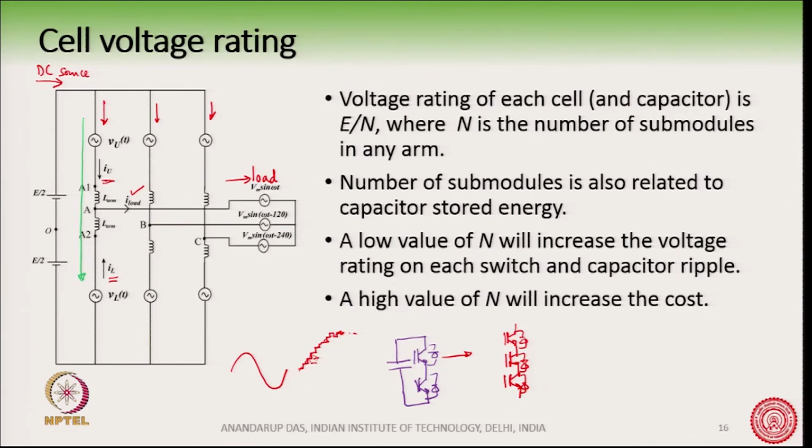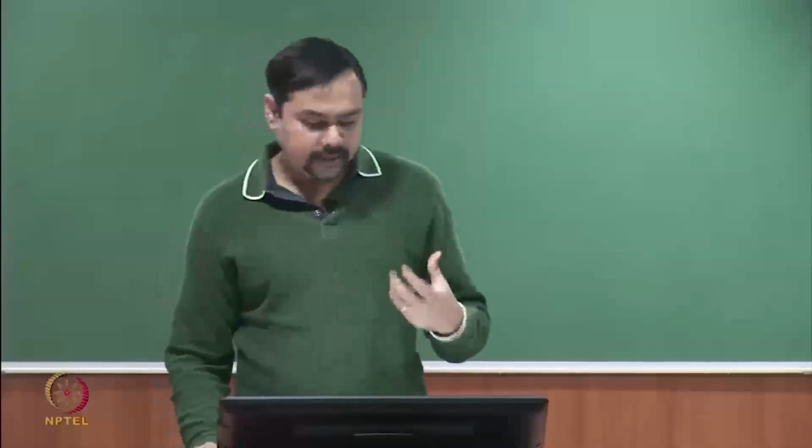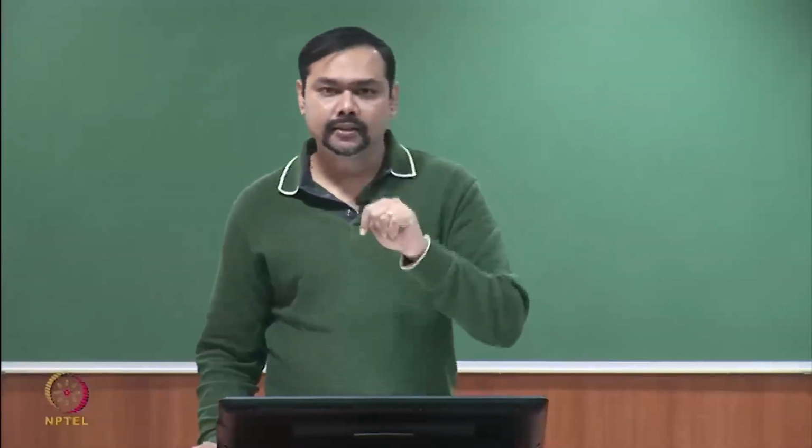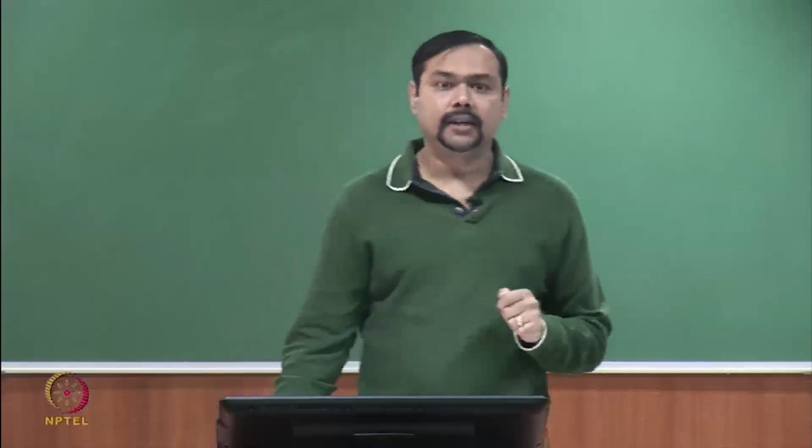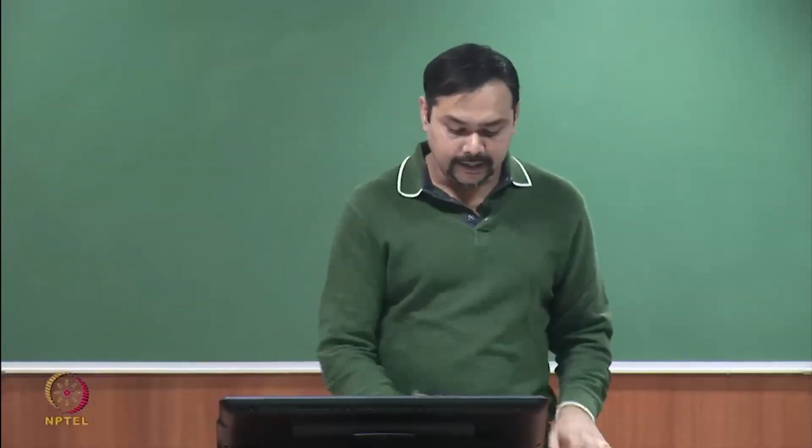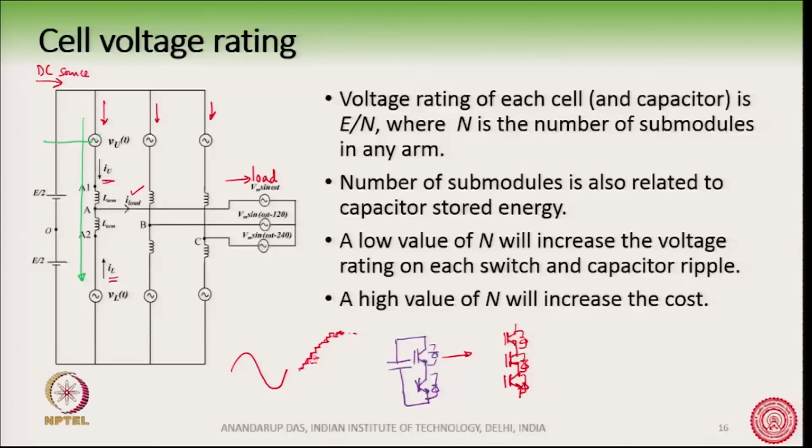It can be compensated, you can say, by a DC current. This is the DC current. Why it is DC, that we will come to. We will show mathematically why it is DC, but there must be a circulating current. This circulating current ensures that the net energy taken from this source over a certain period of time is 0. So, we do not take or give any. This circulating current is essential for the operation of the converter.